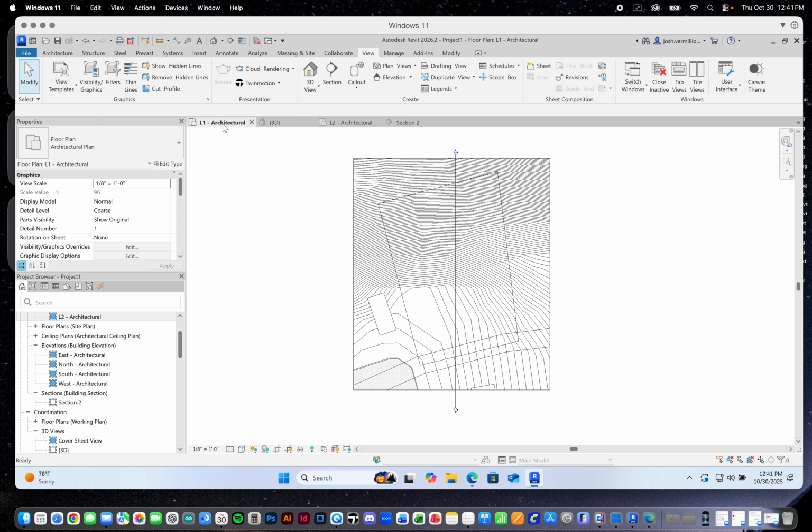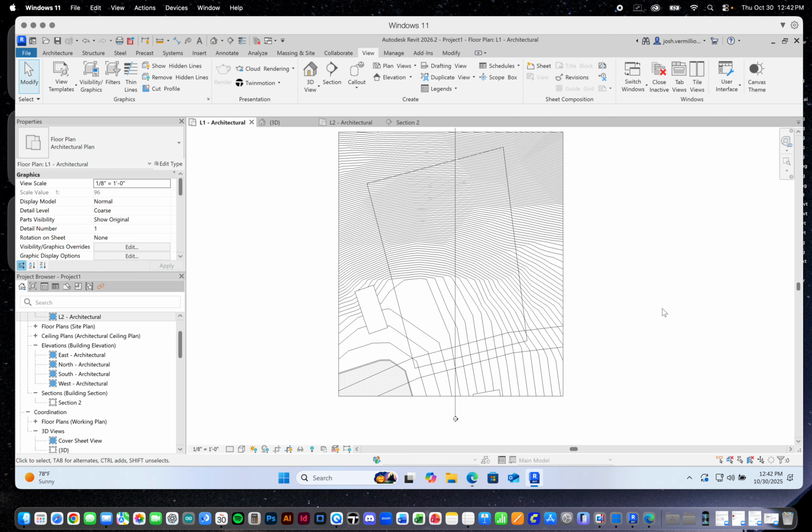Typically, when I'm looking at how to organize a project, I think in terms of axes and grids. And when I'm looking at a rectangular grid, then I start to look at the site constraints, the program, as well as what my structural system, what kind of spans it can achieve, and try to find that sweet spot. In this case, I'm going to tell you we're going to make 3 by 1 bays, running north-south, 24 feet on center, and then the width of the bays in east-west are going to be 36 feet. So let me show you how to do that.